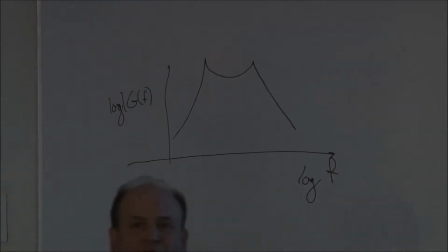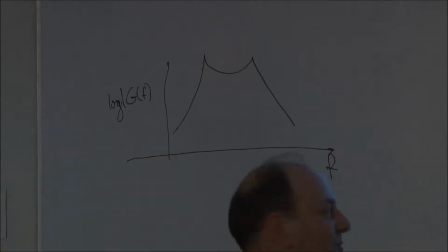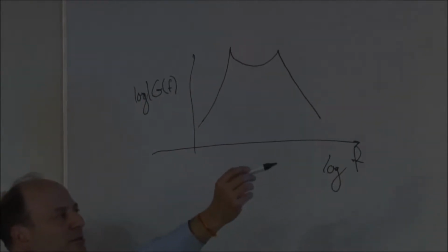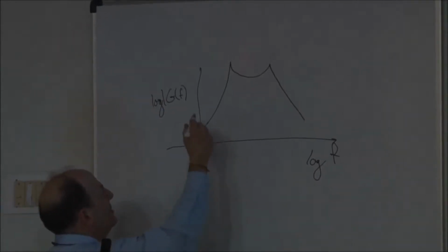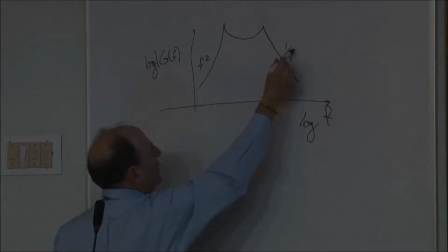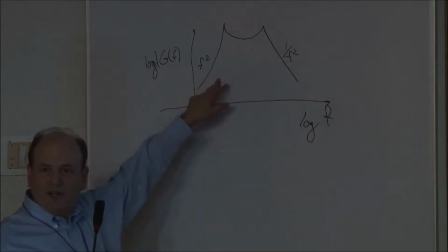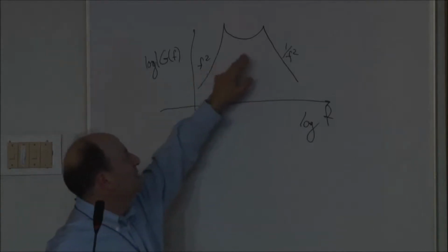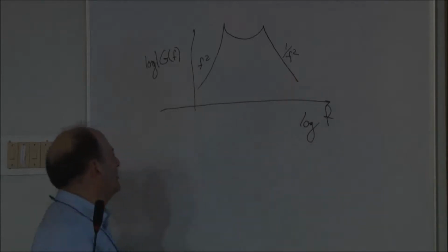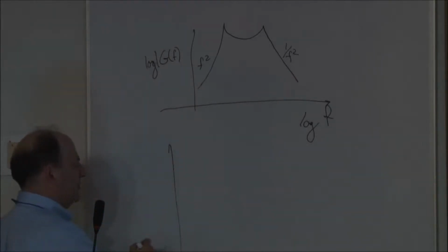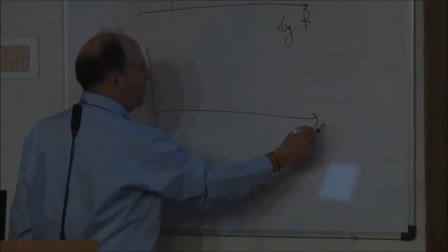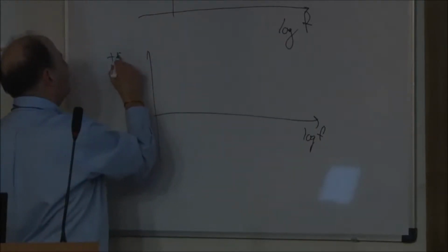There are two modes in this system, two masses on two springs. And the loop transfer function that I've diagrammed there ends up showing those two resonances and having a proportional to frequency squared characteristic below the two resonances, not changing very much in between and falling like 1 over frequency squared above the second resonance. And now here is the phase part of the Bode diagram of G.